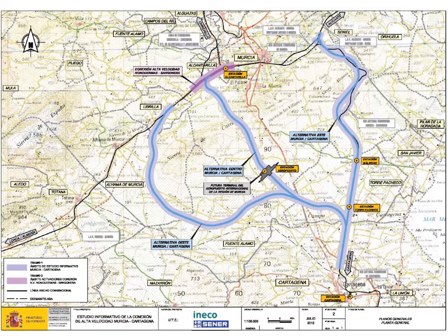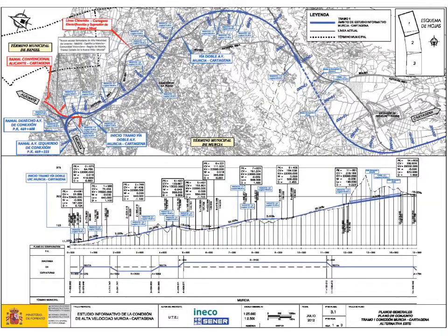So in order to understand what we're going to design, we need to know what the scheme looks like, where it's located. This drawing of a Spanish railway just shows at a very high level the new routes, some of the new stations, key infrastructure, and also how the railway will align with the existing infrastructure. So as we progress with our design, we'll have to look at horizontal and vertical alignments, and we'll have to produce longitudinal sections through the railway. We'll have to pay particular attention to gradients and also the radius of the curves, and that depends on the line speed of the track.